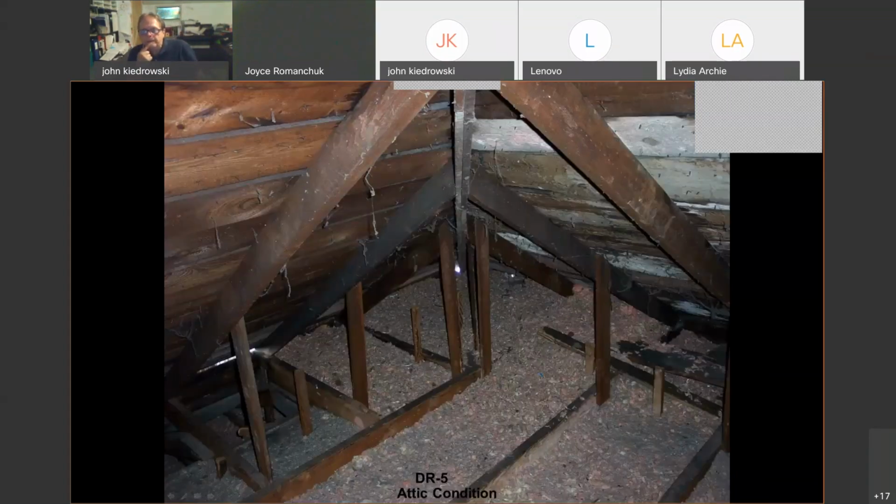And here's a real oldie. What do we do here? We have an old wood frame structure, some old mineral fiber insulation in the attic space. But if you look closely, you'll see some white areas when we look towards the left. That's daylight I see through the fascia and overhang. So areas where, well, we have lots of ventilation, but certainly it's not well sealed and so on. And certainly can cause damage, water and moisture damage to the actual, not just insulation, but to the wood frame structure itself.